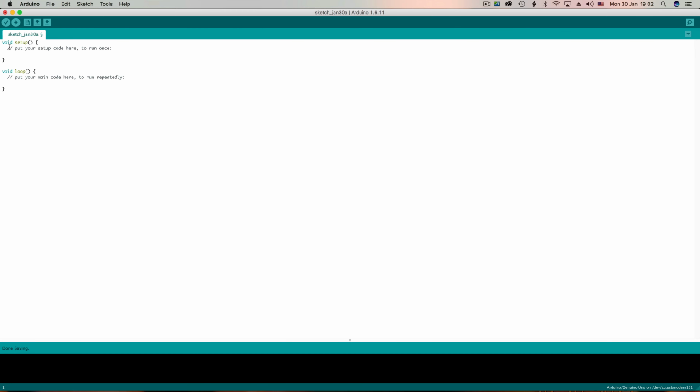Analog outputs are very similar, but have a smaller range in which they can adjust their value. They can be adjusted from 0 to 255. Through this, you can change the brightness of your LED more precisely. Or, for driving an LCD, you can change the brightness of it more accurately, so it will be more suited for the environmental conditions.